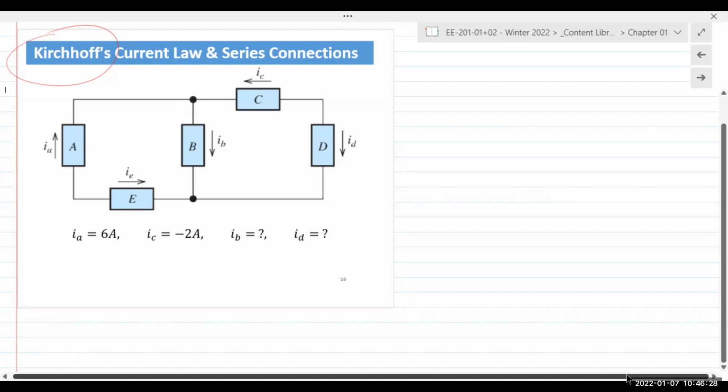There was a German physicist, a researcher, who came up with a few laws regarding current and voltages in a circuit. And they were based on the law of conservation of energy, right? Anyway, based on his work, we have Kirchhoff's current law and Kirchhoff's voltage law, KCL and KVL. Basically, it states when you sum up all the currents around a node or electrical junction, they should all equal 0. If you sum up the voltages around any electrical loop, they should also equal 0.